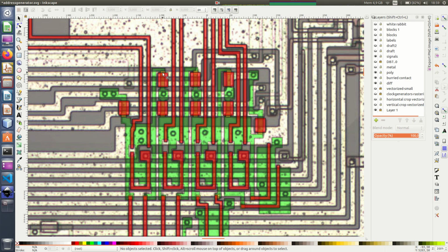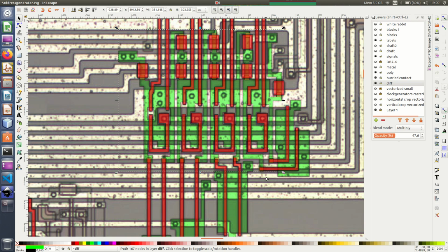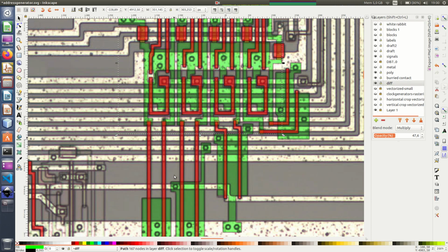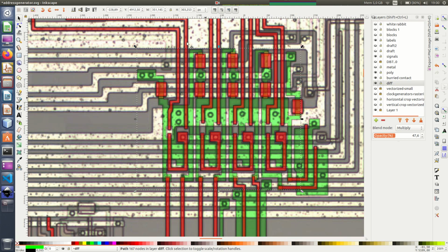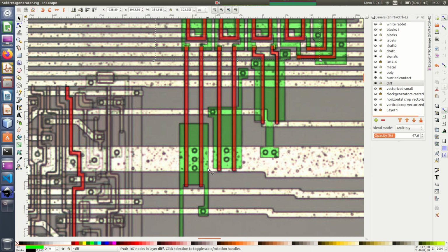There's a pull-up up here, and if all those used transistors are on, that means this network is on anyway, then all of them will disable everything. Everything will be low. All these outputs will be low. So that's an enable. If they are low, then the signal coming from here will be inverted. However, it will come out here. So this driver will actually do something on the internal bus.